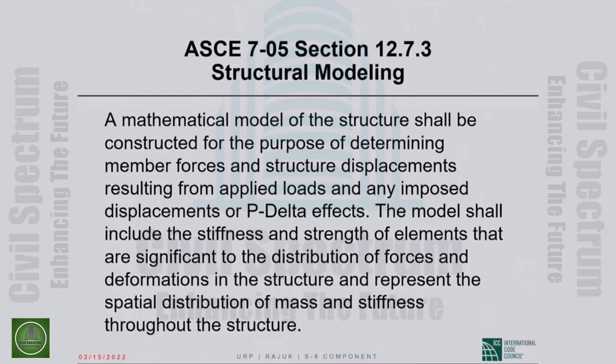Structural modeling. Some of this I think I covered on a previous occasion. A mathematical model of the structure shall be constructed for the purpose of determining member forces and structure displacements resulting from applied loads and any imposed displacements or P-delta effects. The model shall include the stiffness and strength of elements that are significant to the distribution of forces and deformations in the structure. So everything that contributes significantly to stiffness shall be modeled.